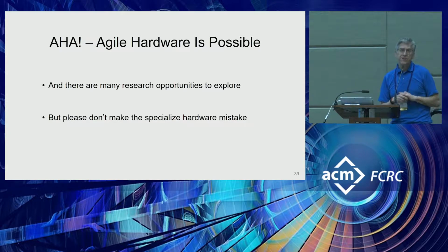There are a lot of very useful formal techniques that are basically specs on interfaces or other things that can then be used for generating random vectors if I can't formally validate the whole thing. But even more importantly, if you put those formal things in, these are basically expect, require kinds of constraints. So you might be able to formally prove something about it because you can limit the legal inputs. And so by putting it in, you help both the test generation and the formal validation.